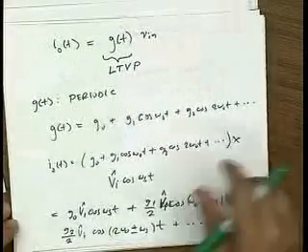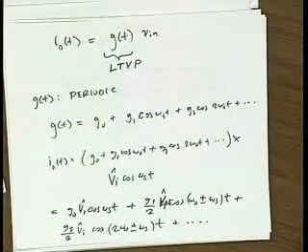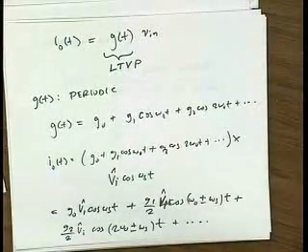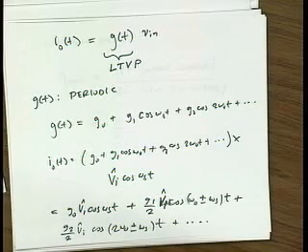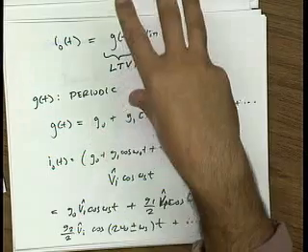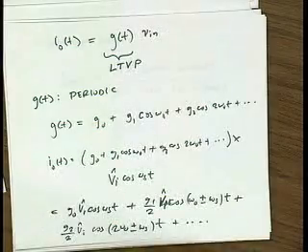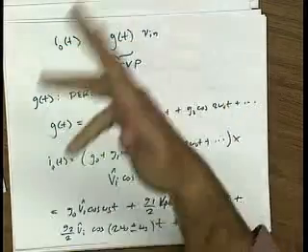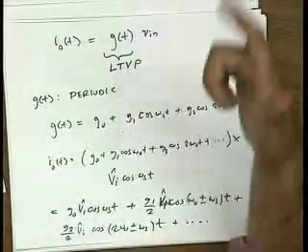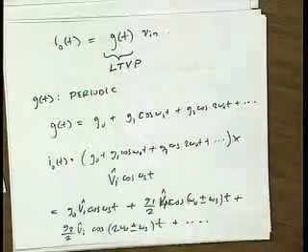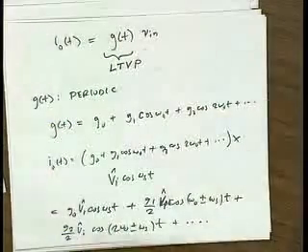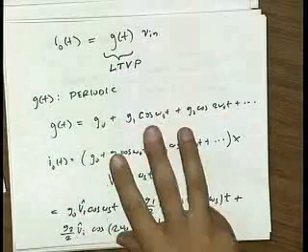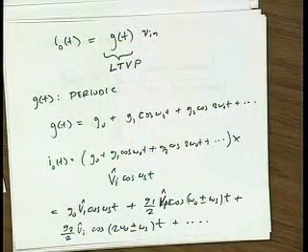I have a question. Yes. If the local oscillator signal is a perfect sinusoid, do these harmonics, 2 omega naught, get generated because of the nonlinearity of the circuit? Yeah. Even if we assume that the LO is a perfect sinusoid, we did that when we looked at the large signal behavior of a differential pair or a single transistor, and even there we get harmonics. But actually, for this analysis that we just did to be valid, all we have to assume is the LO is some periodic function. It doesn't necessarily have to be a sinusoid.